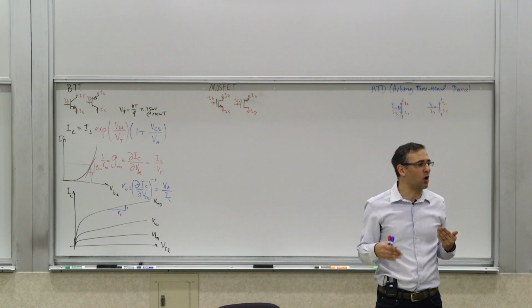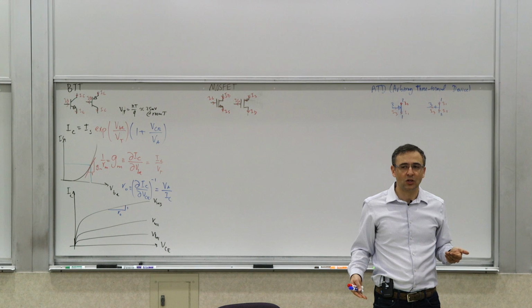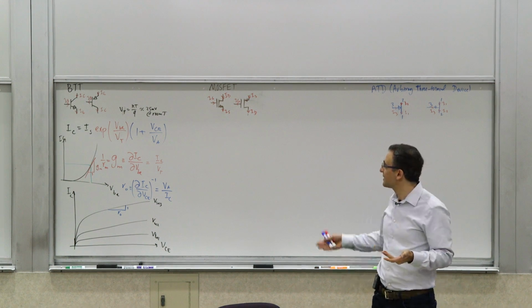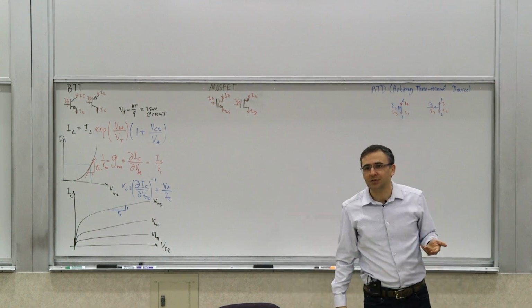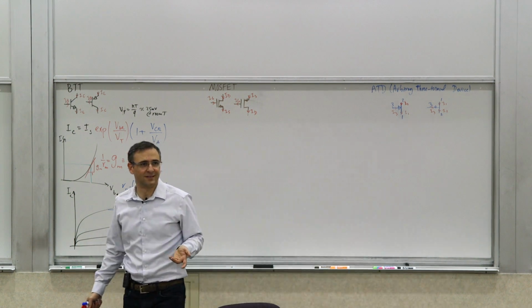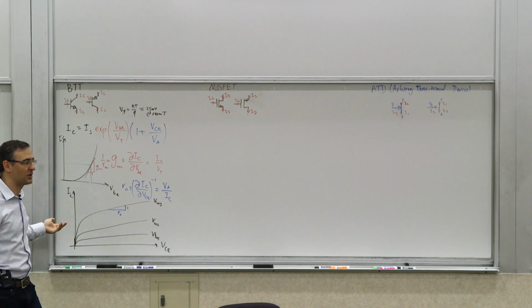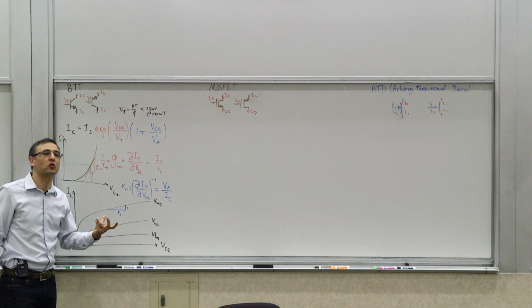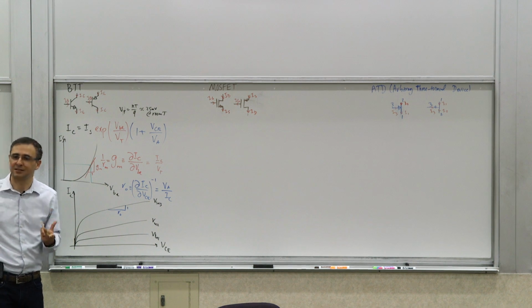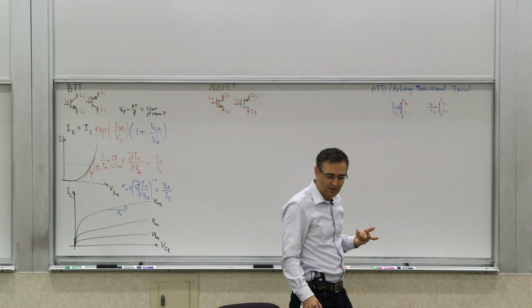RM and RO are both inversely proportional to IC. So the ratio, as you can see, is VA over VT, which is independent of the collector current. And we'll see that this ratio is very important as we do our development. It's actually something fundamental that tells you how good a transistor is in certain ways. And we'll see why in a second.